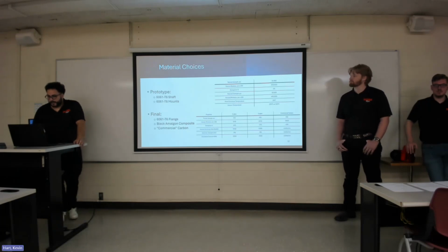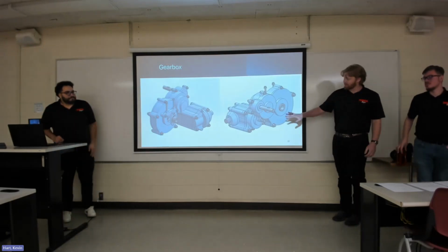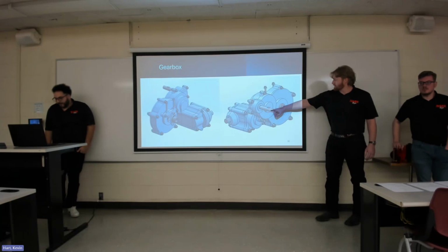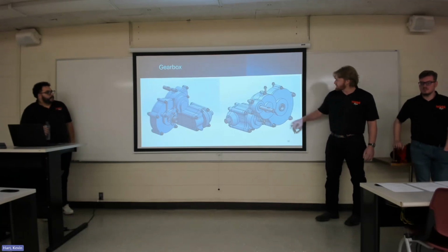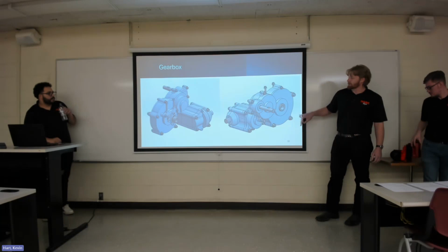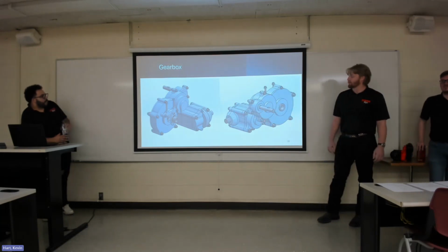And then moving into the gearbox. All right, so for the rear gearbox, I included a couple of big pictures so I can get you familiar with the system a little bit. So this shaft here will be where our CVT input is, and then down here, and you can see it in the other view, will be where our drive axles will come out, and then this is the split to go up to the front wheel drive portion.